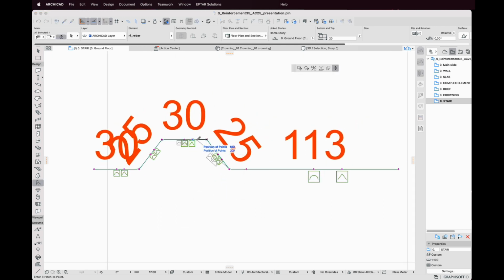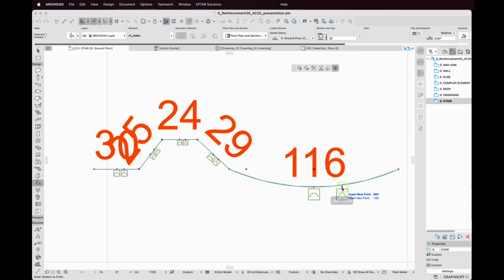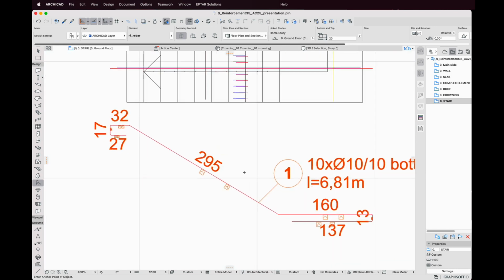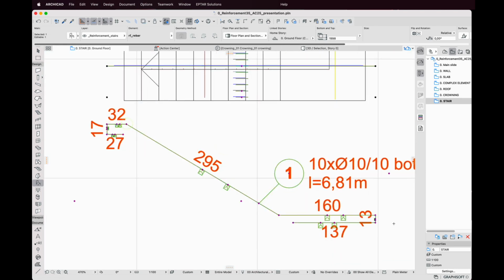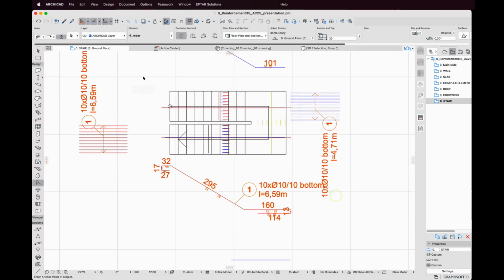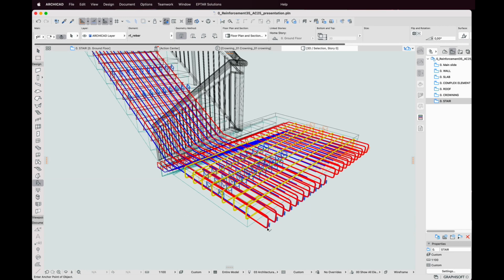I can make the straight part curved, or I can add new hotspots to this section. It shows that almost any shape is possible to create. I did the same modification of the rebar, I just adjusted points of it to the stair geometry. Now to see it in 3D. There are straight rebars on the horizontal parts of the stair, and here there are slanted rebars.